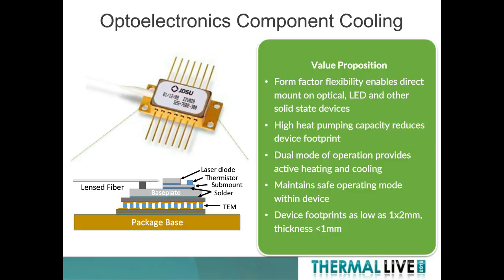Yes. So in this case, it's for stability of the temperature. I just want to make sure I point out for the listeners that one of the nice benefits of thermoelectric devices is that they can be used in opposite polarities to heat and to cool, with good efficiencies for heating, and sometimes even better for cooling. So I just want to make sure we point that out for the listeners.